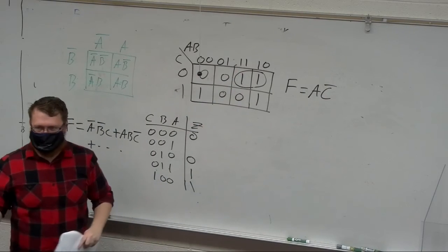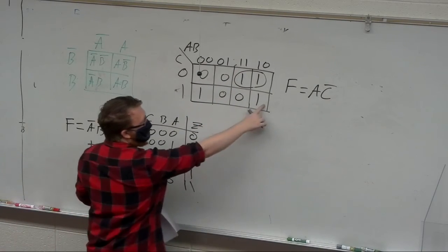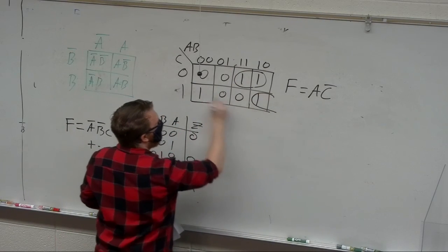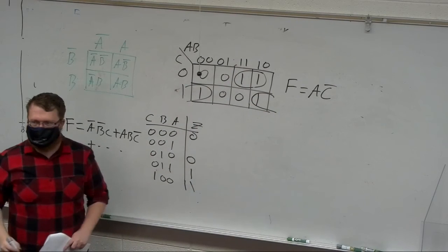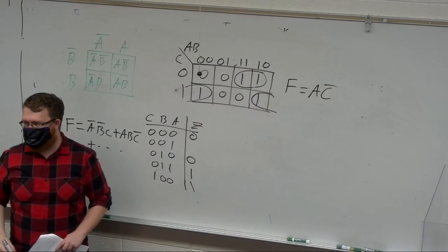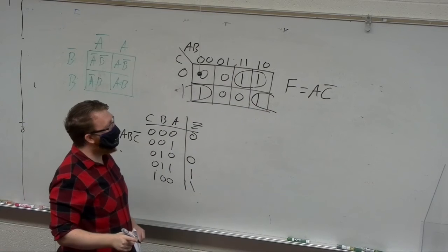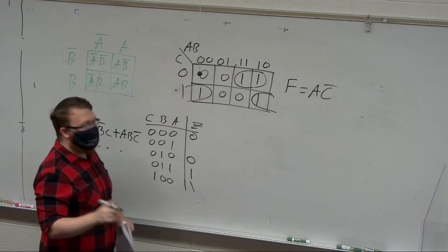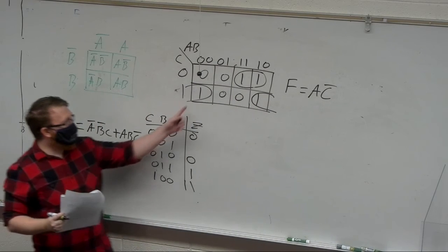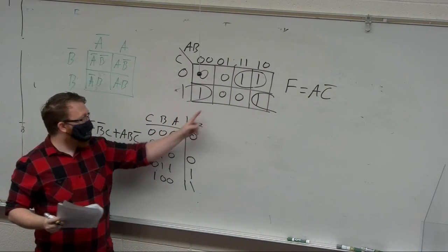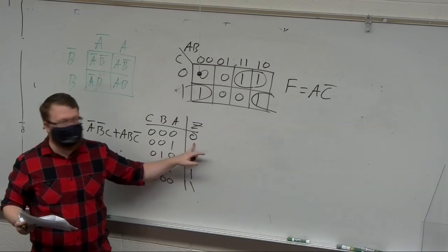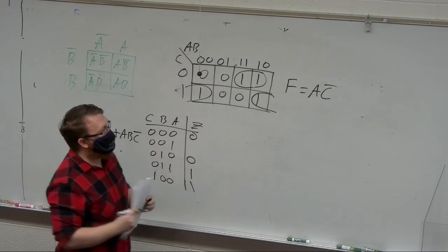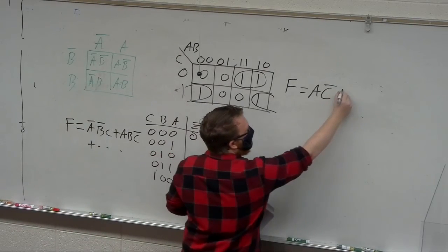Now, this is where the cool part comes in, because this and this are logically adjacent. I can have a circle that goes around the K-map. Can you do the same for max terms for the knots? Yes, exactly. So what he's asking is about max terms. The ones are what we call min terms. Zeros in a truth table are max terms. You could circle zeros instead of ones. Well, let's keep with the ones for just a moment.